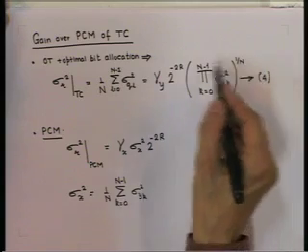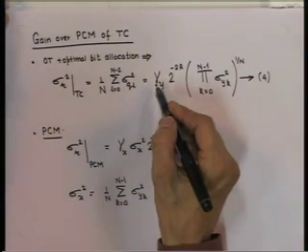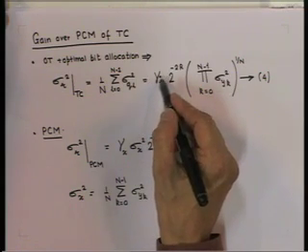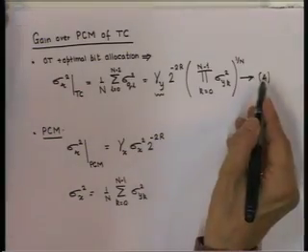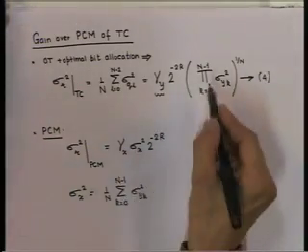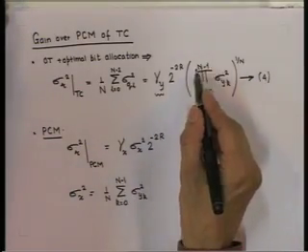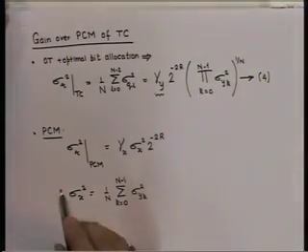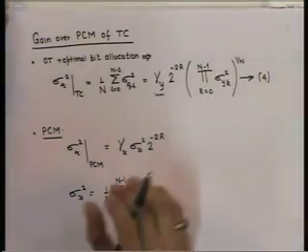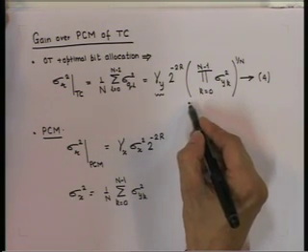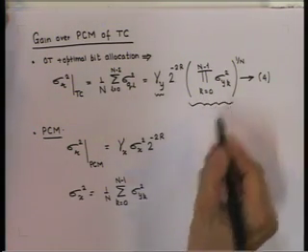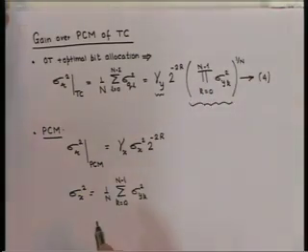Now, coming back to this expression, if we ignore the effect of transform choice on uniform quantizer efficiency, that is gamma y, then this expression 4 suggests that transform coding reconstruction error can be minimized by choosing the orthogonal transform T that minimizes the product of coefficient variances.